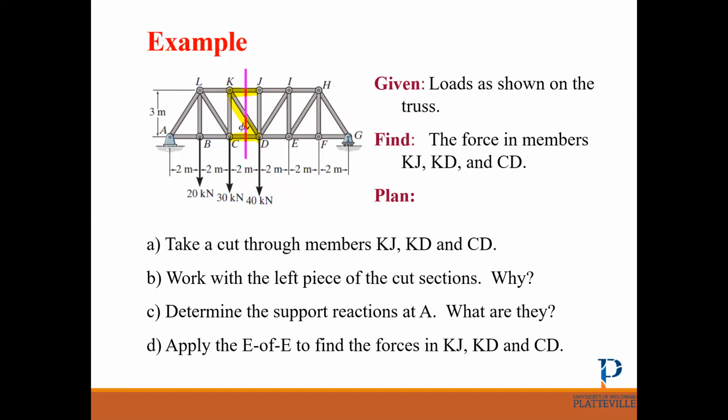Then the next step is to think about whether we want to analyze the right part or the left side. This depends on us, which section is easier for us to analyze. Then determine the reactions and then apply the equilibrium equations. So at this point, stop the video and find the reactions first. Then draw the free body diagram for the left side and see how you can apply the equilibrium equations.